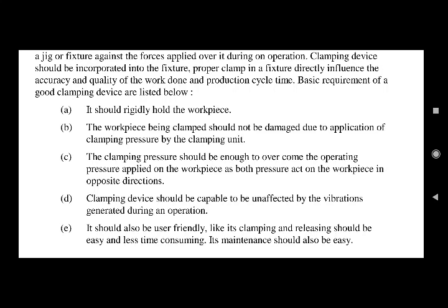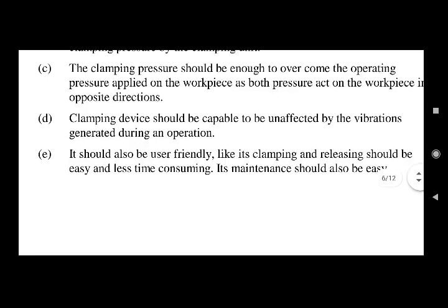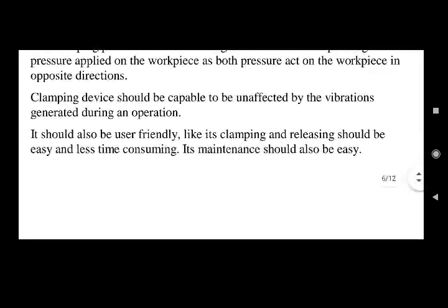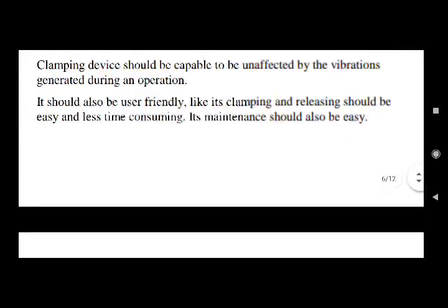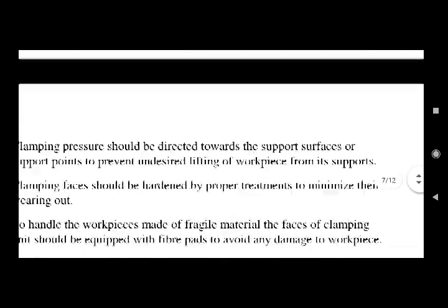The workpiece being clamped should not be damaged due to the application of clamping pressure by the clamping unit. The clamping pressure should be enough to overcome the operating pressure applied on the workpiece, as both pressures act on the workpiece in opposite directions. The clamping device should be unaffected by the vibrations generated during an operation. It should also be user friendly, like its clamping and releasing should be easy and less time consuming. Its maintenance should also be easy.